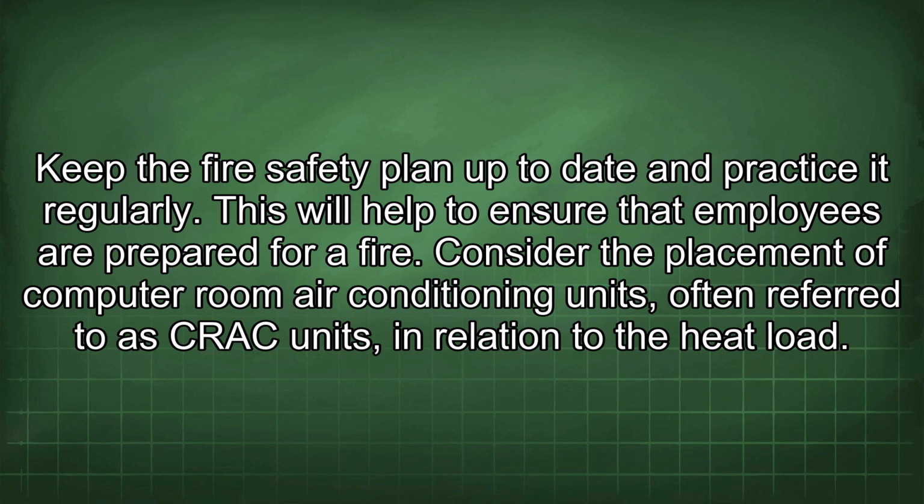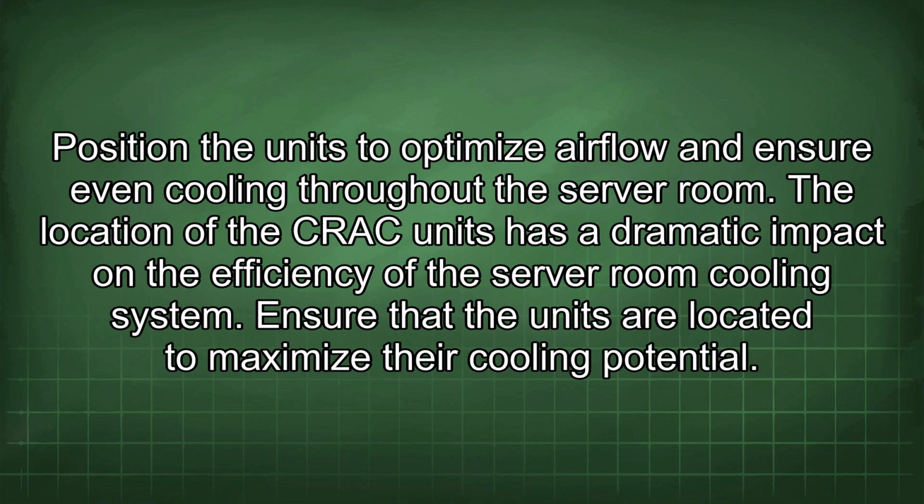Consider the placement of computer room air conditioning units, often referred to as CRAC units, in relation to the heat load. Position the units to optimize airflow and ensure even cooling throughout the server room. The location of the CRAC units has a dramatic impact on the efficiency of the server room cooling system. Ensure that the units are located to maximize their cooling potential.